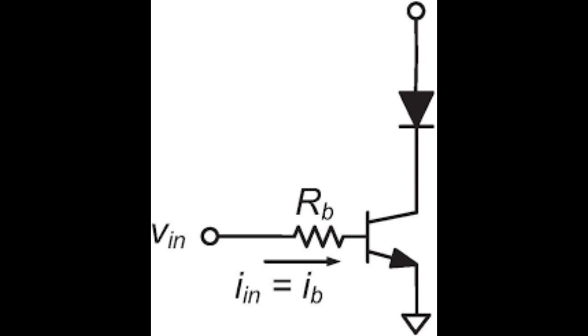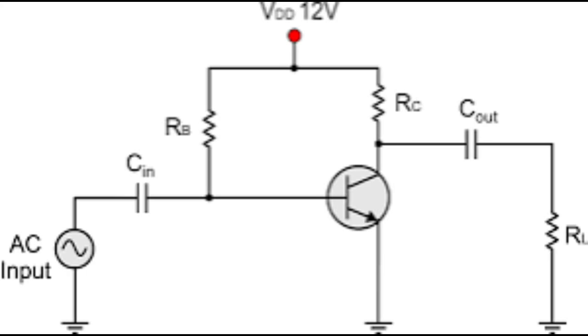be forward biased. Base is approximately 0.7 volt higher than the emitter for silicon BJTs, and the collector-base junction must be reverse biased. Collector is at a higher voltage than the base, typically VCE more than 0 and VBE approximately 0.7 volt.